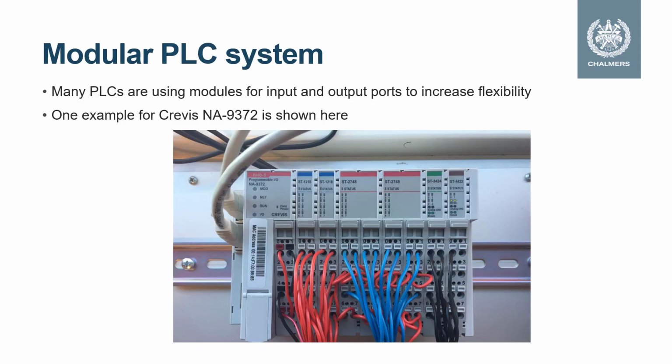This is a photo of the Crevis system that I have in my lab. I will be using it as an example of a modular PLC system. We can see that it's modular here. Each module can be removed, put in another place, and they are all connected here. Many PLC systems are modular, which means that they are very flexible. If we want to have more input modules, we can just put one extra in.